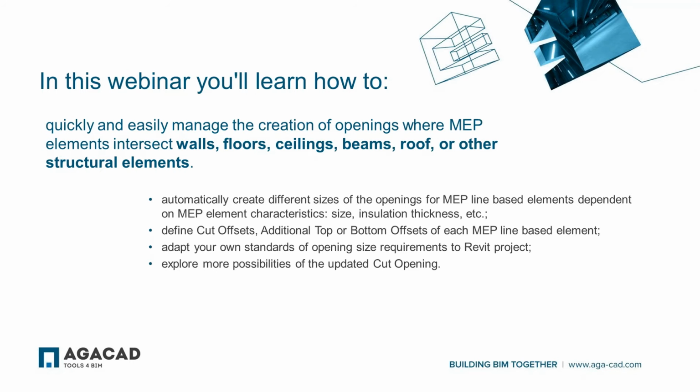In this webinar, you will learn how to quickly and easily manage the creation of openings where MEP line-based elements intersect structural elements like walls, floors, ceilings, beams, columns, roofs, etc. We will also learn how to automatically create different sizes of openings for MEP line-based elements depending on characteristics like size, insulation, thickness, etc. We will learn how to define cut offsets, additional top or bottom offsets for each MEP line-based element.